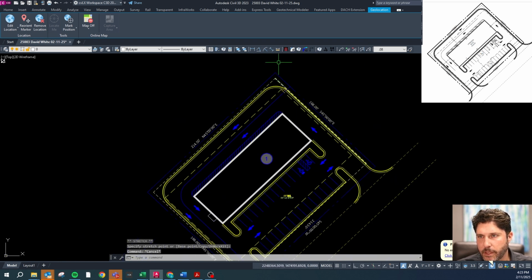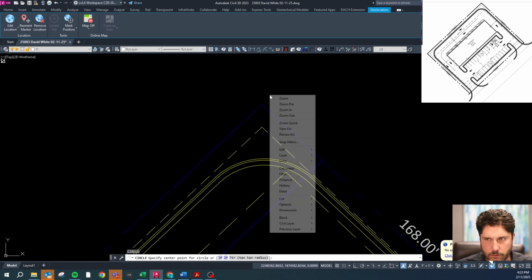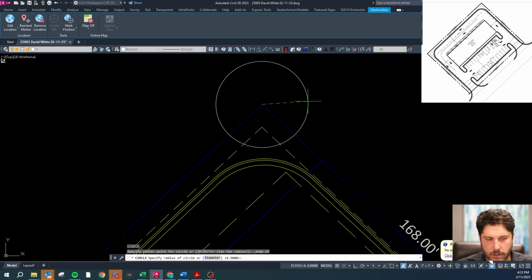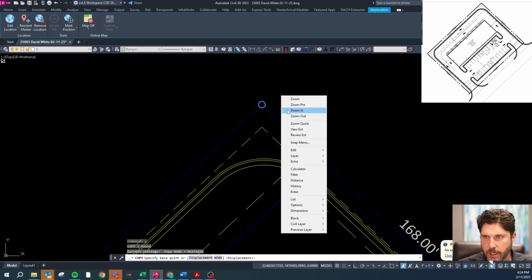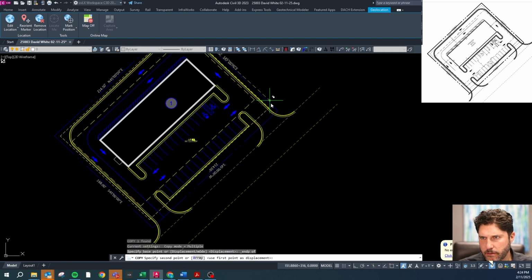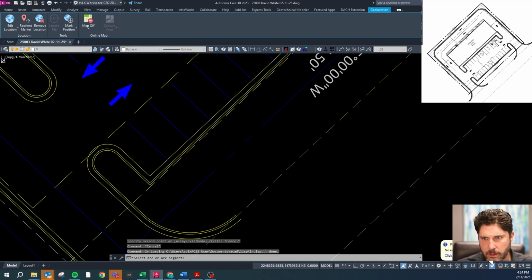We do want our property lines where the diameter is equal to 1/10 of the scale, so 20 scale, diameter of 2, and then that will go on the same layer. Actually, I just did a radius of 2. Let's change that diameter to 2, and we'll copy from there to there to there to there, and let's do a little LR label radius.